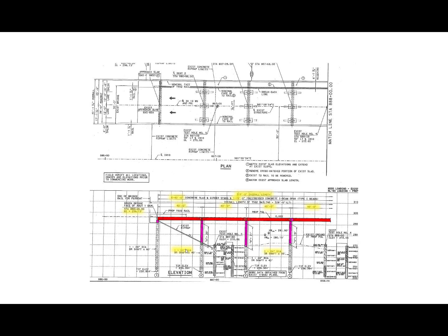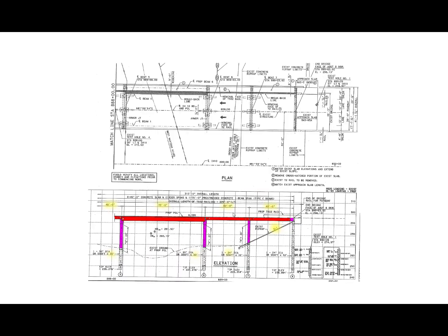All the piers are 24-inch diameter piers at the 40-foot spans. We go to the next sheet, we'll notice that there's a 75-foot span, which is flanked by 30-inch diameter piers, and also has a little thicker bridge deck. And then we return back to the normal section, which is the girder section, and the piers change back to a 24-inch diameter.